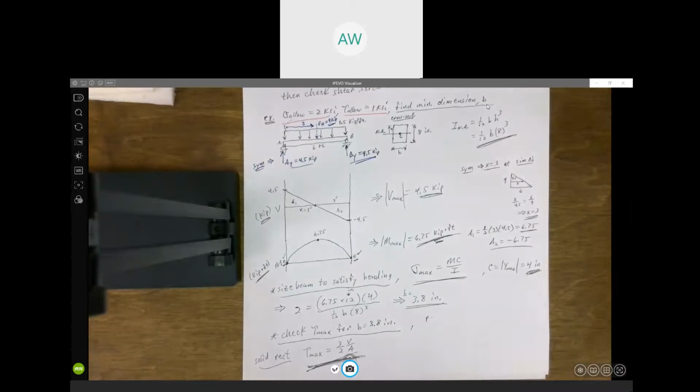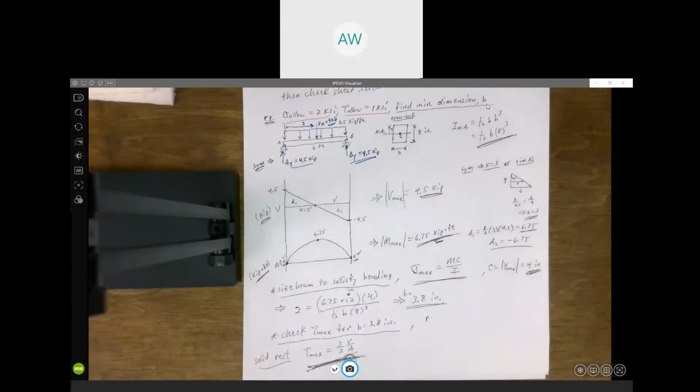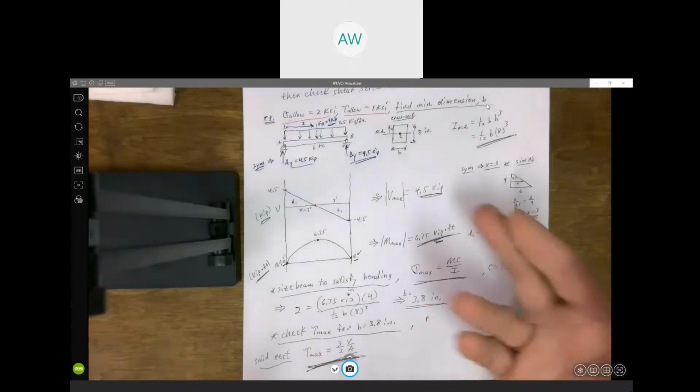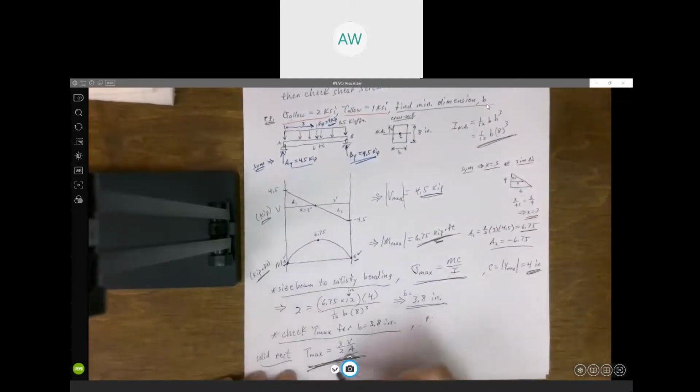If you do, it comes in handy when you have a rectangular cross section. You don't have to calculate what Q is, and we've already calculated I, so basically all it does is save us having to calculate Q. But for a rectangular cross section, finding Q is not real difficult. So if you don't remember this formula, you could always use tau equals VQ over It.